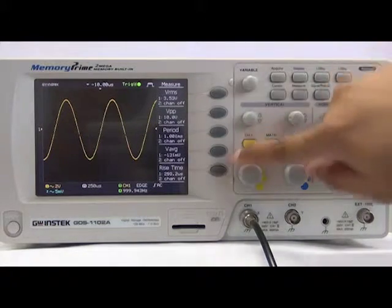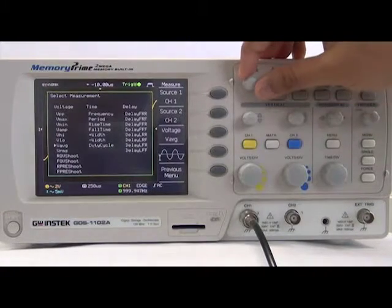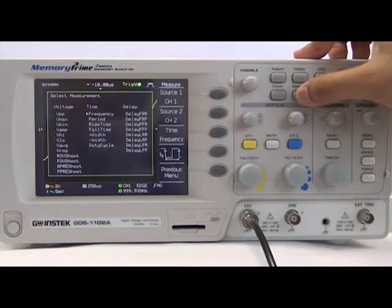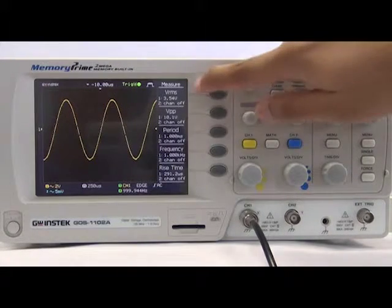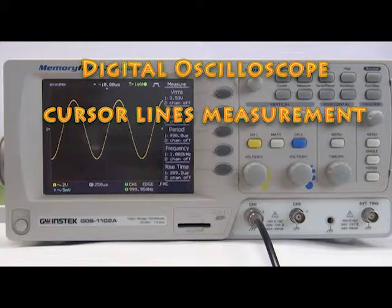Next, change it to frequency and turn the variable and press measure. Now you will see all the four components being displayed perfectly. Task 4.3 is to measure the input signals using cursors.